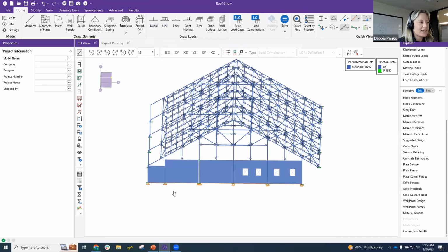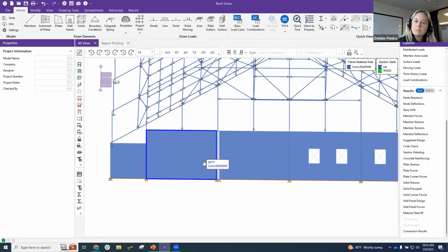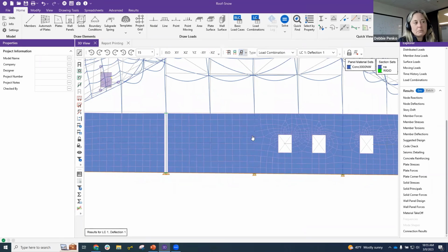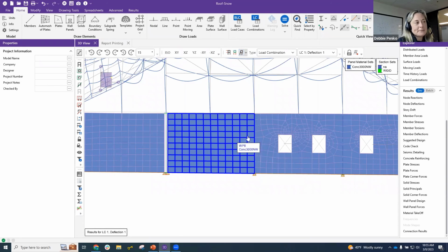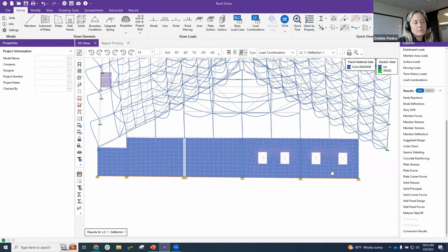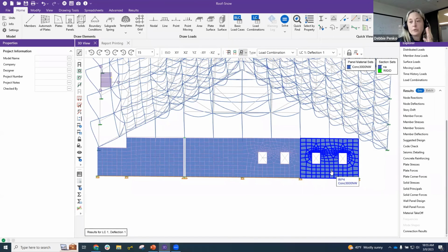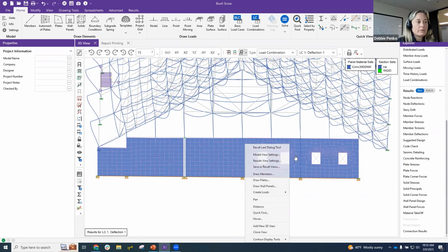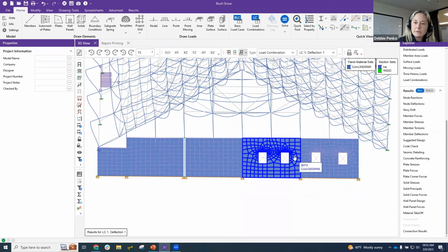So we always say, unless you do this type of separation, because really what's happening is that plate meshes are tying it together. We've seen it much more in wood, specifically because wood cannot take out of plane load as well, so you don't have the resistance, but concrete and masonry inherently have the ability to take in plane and out of plane forces. So for that case, you'd have to separate it.